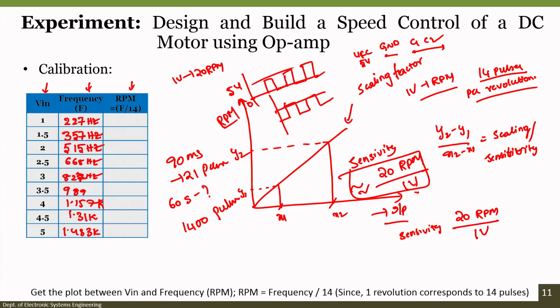As a result, we see a reversed signal, a 180 degree phase image, or flipped version of the actual signal. We will come back to why this is required. That is why the CRO output is shown as 0 to minus 5 volts, but the frequency remains the same. What changes is the duty cycle.